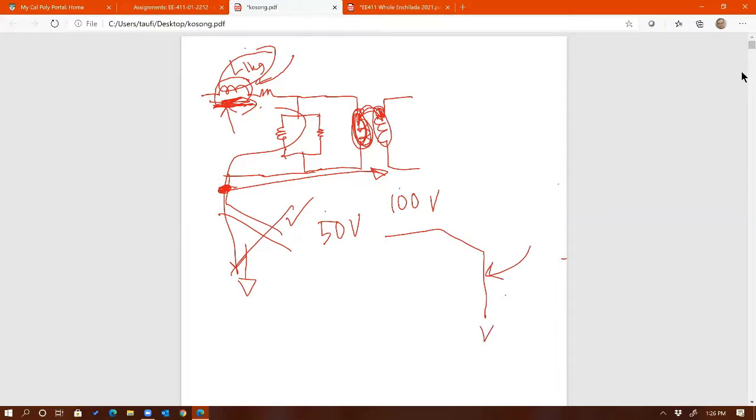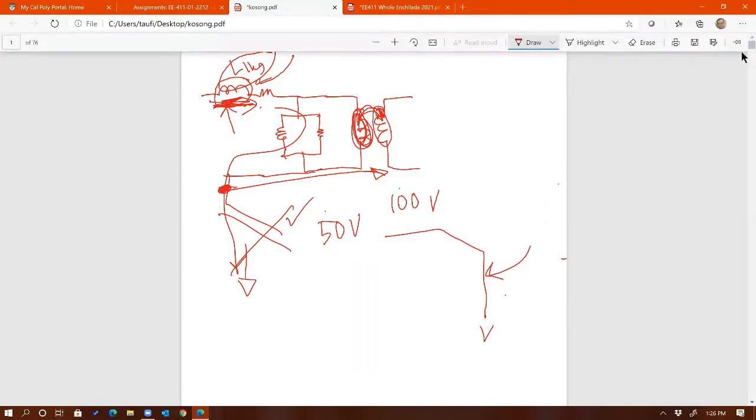Is this the same reason you have to put diodes across, like if you're driving a solenoid with a MOSFET, you have to put a protection diode across it for reverse current? Exactly, exactly. That's for freewheeling. We call it a freewheeling diode, right? Otherwise, you're going to get voltage building up across that inductor until something blows. So you have to have that diode protection for freewheeling, right?